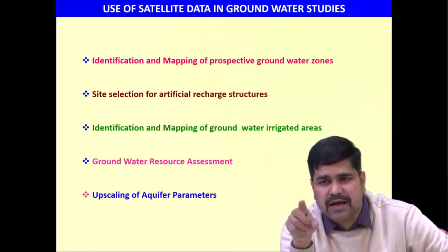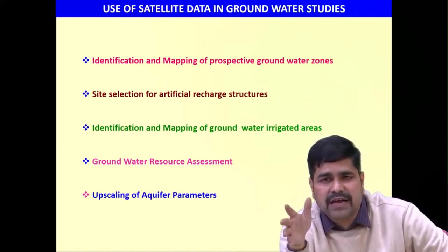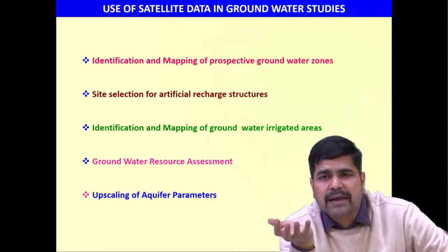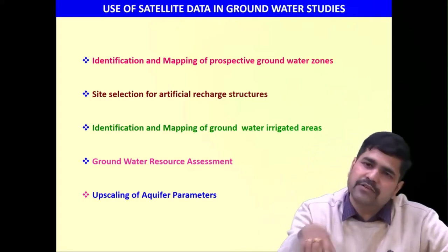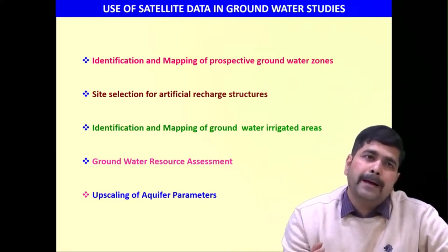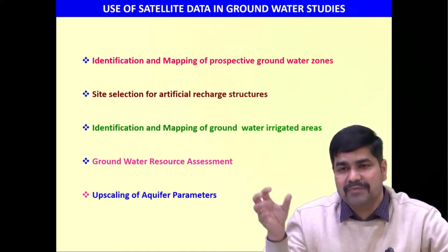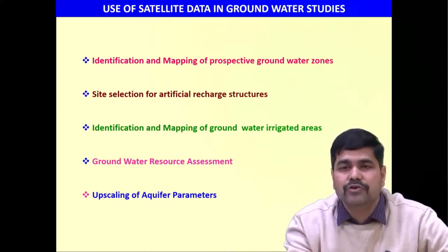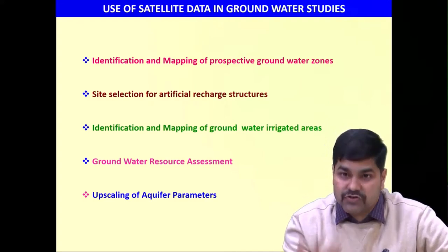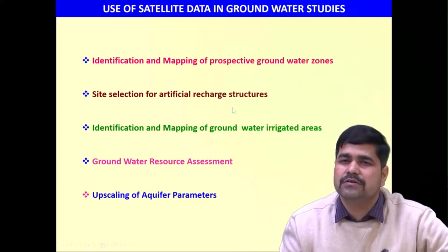And if there is a structure, by the term structure I mean that it's bound by some impervious membranes or dikes or a fault, something like that, so that there is already a bed which can hold the groundwater. If it can hold the groundwater, then when you recharge it, the water remains there. If by some means you can draw the water available in the monsoon onto this bed, then because it is underground, you can reuse it in winters or summers where there is a need of water. So that's how the selection of artificial groundwater recharge zones works.